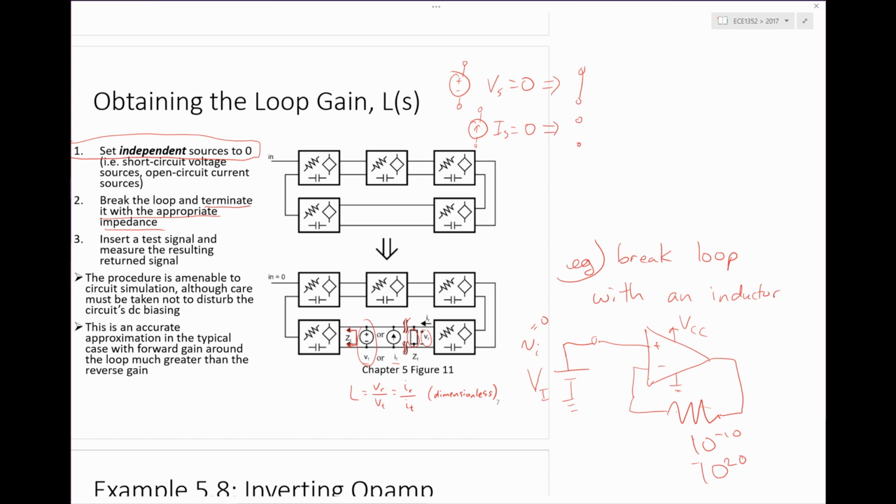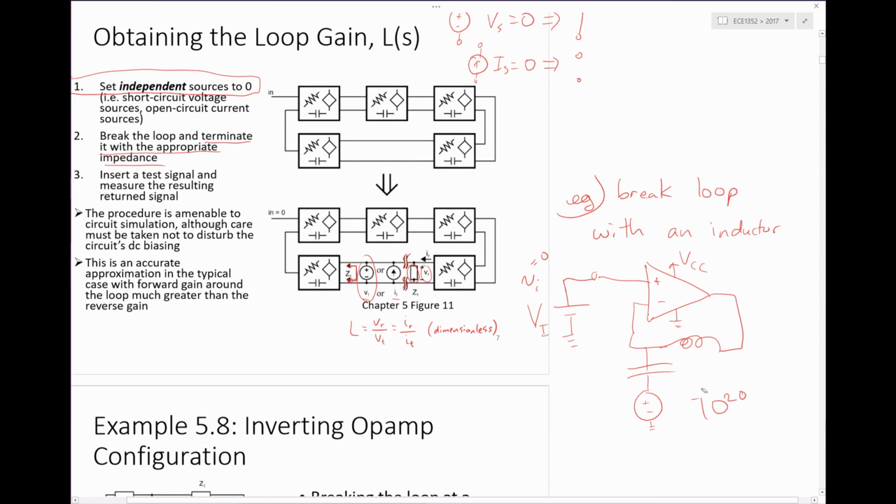I forgot that. So you're right, because for the AC analysis, you've broken the loop. So even for the resistor method I showed, your point is right on. Okay, so I'll stick with this for now. So what about, let's say, looking in here, you've got a capacitance CI, an input capacitance looking in there. Yeah, you should connect that here. That'd be part of the loop. Anything else you want to say about that?